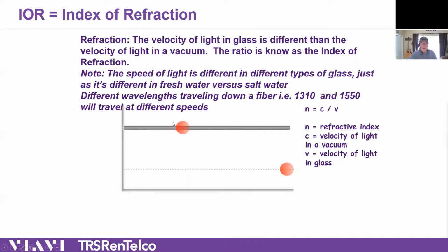And then we look at the process from the manufacturer of the fiber, and we can calculate the speed of light through that fiber. And knowing that phenomenon is why your OTDR can tell you how long a fiber is, just by shooting it from one direction, right? So I'm standing here and I want to shoot something, I don't know, 10 or 13 or 14 miles away. I don't have to have a unit on both sides. I just shoot it with the OTDR.